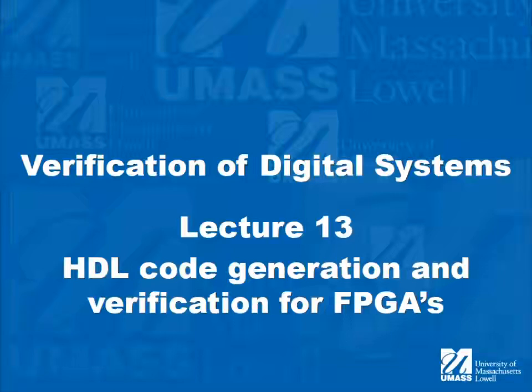You can get an FPGA development board for like $80, various ones. That's kind of the low-end price point. Go through the software and do this, right? Even just throw an adder in there, but build stimulus, design a response checker, and run the algorithm through it. And see how fast it goes, and run the same thing in simulation, right? The same stimulus, same response checking, do that in simulation.